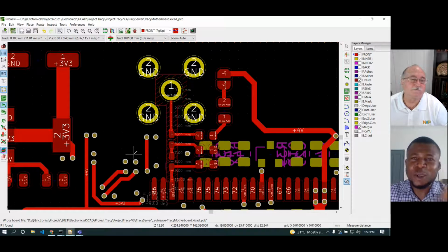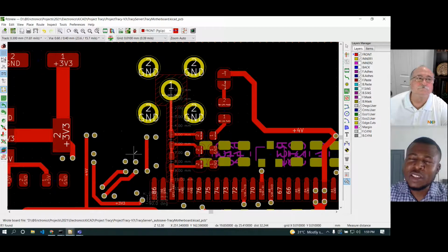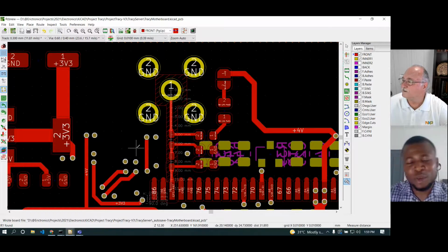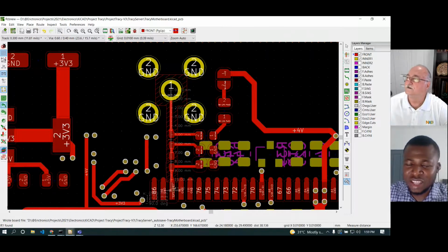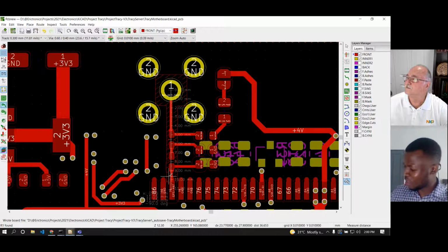So typical of GPS, I think the frequency is about 1500 megahertz. So does critical length of the trace come in here? Because this is an impedance control line, like I said, and I don't know whether the length, I have to probably calculate at what length it will be critical. 1500 megahertz, you said? Yes, I think that's part of the range.